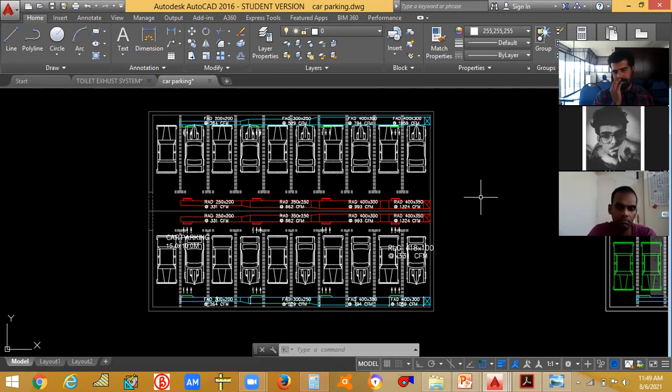In those cases, normally we will be giving many supply fans or many return fans. In that case, all the fans will be working. In other cases, only 2 or 3 will be working in between. So in 12 ACH, all the fans will be working. Normally you give 6 ACH. When there is smoke or something like that, there is a chance of it being produced, so just give 12 ACH or 10 ACH like that.